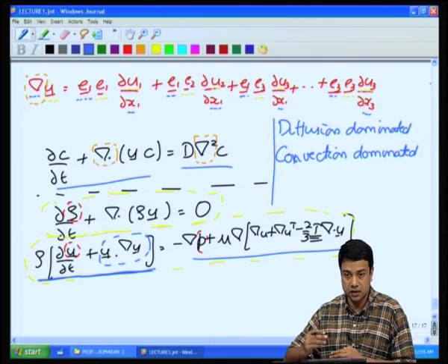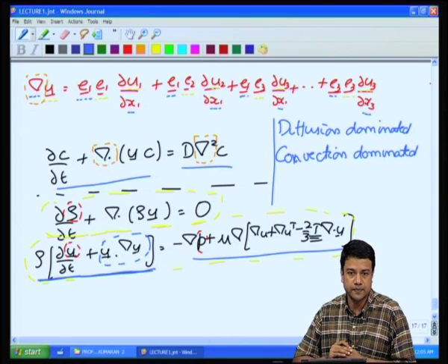This is the boundary layer theory that we had used in part 1. In this particular case, it is a little more complicated, because even if you neglect diffusion, you can still get non-trivial solutions because there is a pressure here. However, with just a pressure field, you cannot enforce tangential velocity boundary conditions at the surface. For that, you still need to postulate a boundary layer.